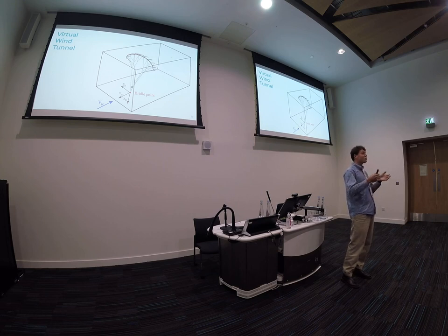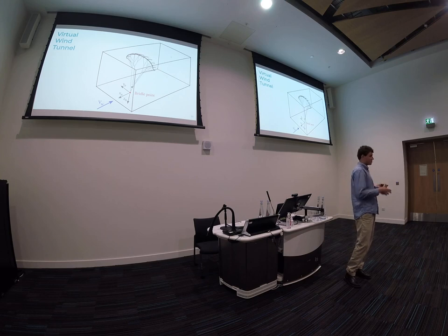Well, because there's only a ball joint constraint at the bridle point, there's nothing to restrict the kite from moving away. So it will start a perpetual turning motion around the bridle point, and it will just start rotating and rotating and rotating. And the rotations aren't physical because it doesn't rotate with its actual radius, it's rotating around the bridle point. So both the simulations don't converge, and so what the simulations show is not physical. So how can we resolve this?